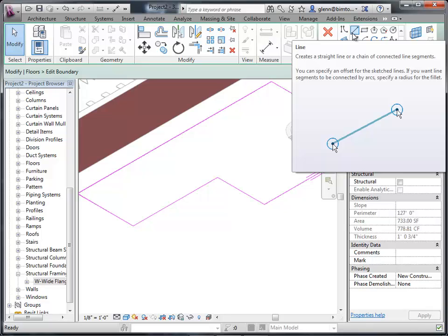Now, Rich, can you cancel out of it? So it looks like there is something going on. Say no. Close again. Go to the drawing tools up here. So that one actually goes. I think it'll let you do it now. What happened is you were picking a wall, and there wasn't a wall you were picking on. Now you're drawing the boundary. So, that'll be okay. Okay, so when you draw, and we'll do that one first, then we'll pick the walls.